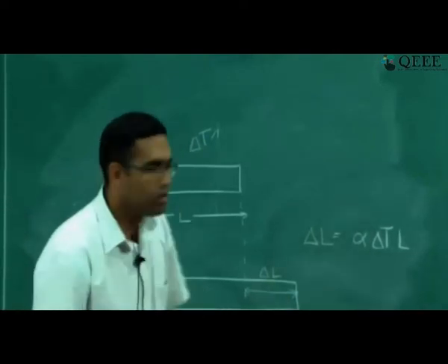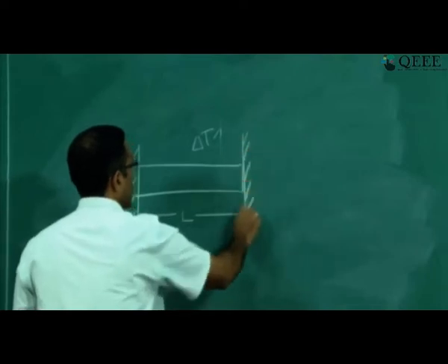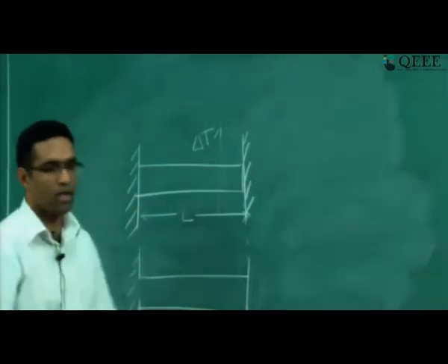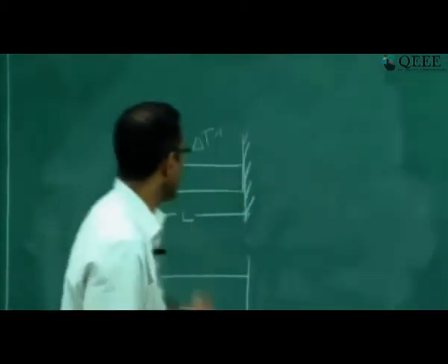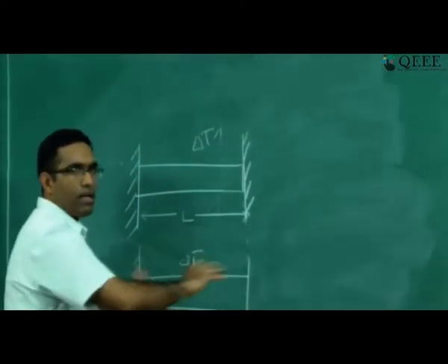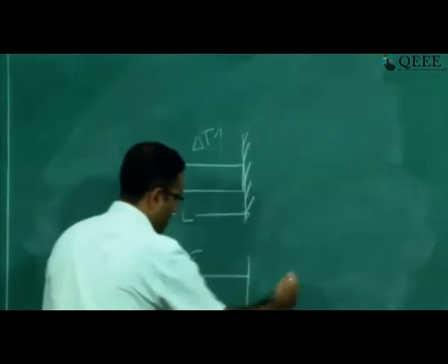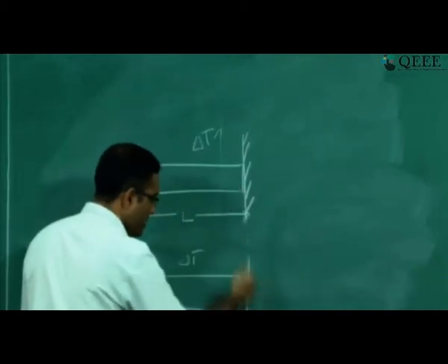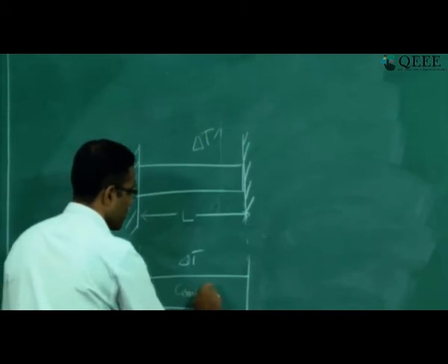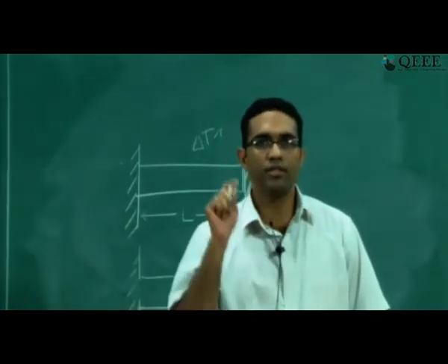However, if I now fix the other end of the bar also and then heat it, the body does not change its length at all, because I am fixing the other end. Assuming that this is just a bar and it is not going to deform like a beam, the bar is trying to expand, but I am preventing the deformation by fixing the other end, because of which some sort of compressive stresses get induced. So only if the body is going to resist the deformation will you have stresses getting induced.